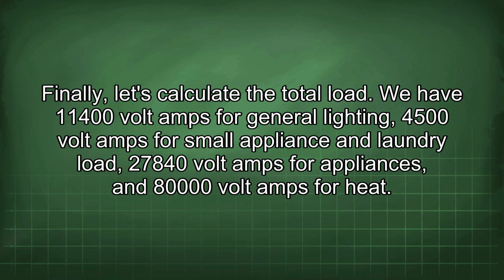We have 11,400 volt amps for general lighting, 4,500 volt amps for small appliance and laundry load, 27,840 volt amps for appliances, and 80,000 volt amps for heat.